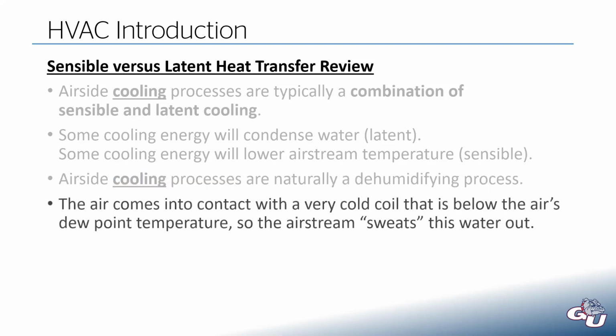The reason being, the air that's coming in is hitting a very cold coil in that airstream. And that coil is typically below the air's dew point temperature. And so the airstream actually sweats water out.